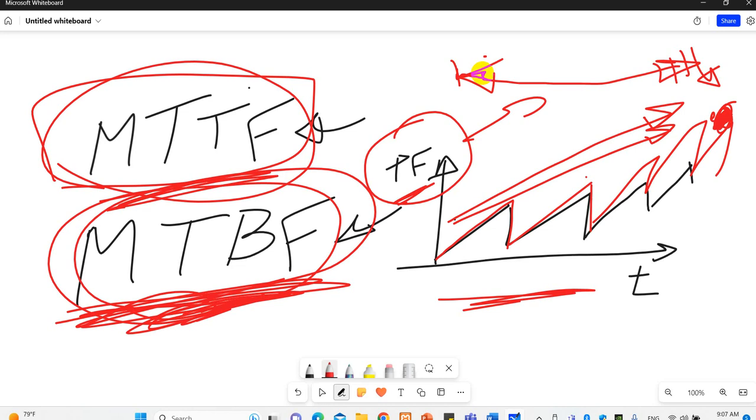For a turbine, are you replacing the turbine or the turbine shaft? Are you replacing the shaft or do you repair it? You may replace blades, you may replace all of these things. Like for a turbine, when we talk about repairing the turbine plates, you have some tables for this repair. You can repair these plates maybe 1, 2, 3 times, but you can't keep repairing forever. At a certain time, you need to replace these plates, right?